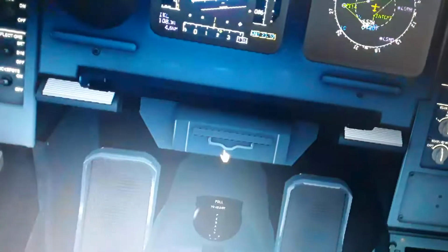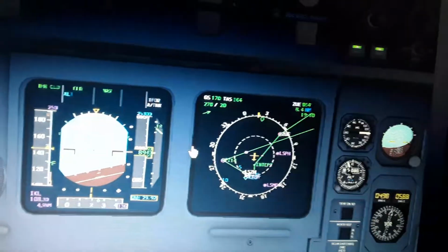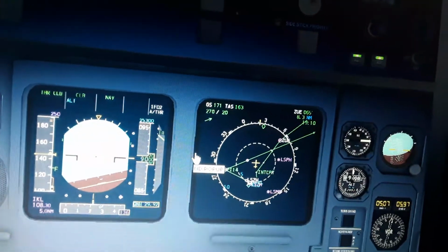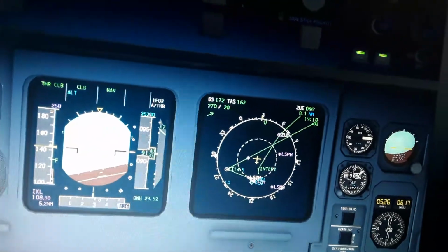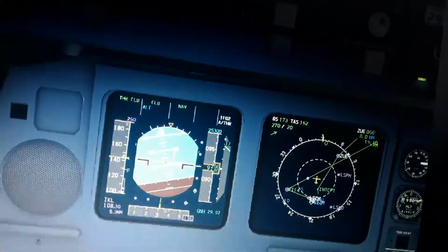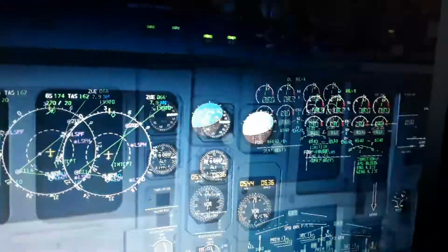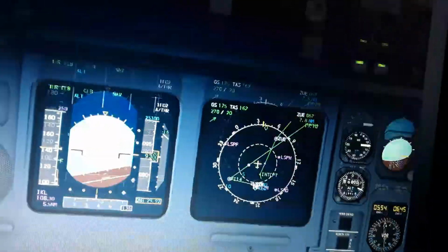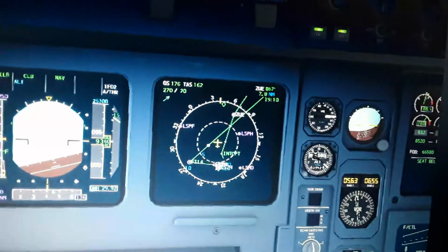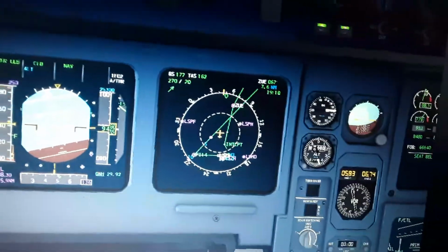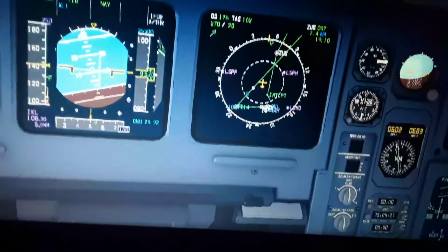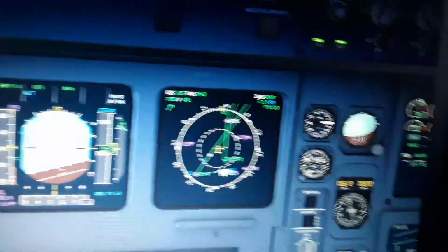This is the fly-by-wire that I was telling you about, using the side stick, which orders the primary flight computers to move the control surfaces. But the primary flight computers are trying to manage the flight by holding zero load requests and limits. It's quite complicated. I have to read a little bit and explain it.